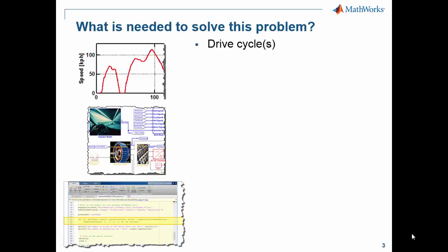We're going to maximize the fuel economy over a US-06 drive cycle. This drive cycle was chosen as it will induce a rich set of operational modes as a result of the aggressive acceleration and braking profiles that it contains. Kevin has already demonstrated where in the Simulink model such drive cycles are defined, and in this case I'm also going to benchmark the vehicle's 0 to 60 miles per hour performance prior to the US-06 standard cycle.